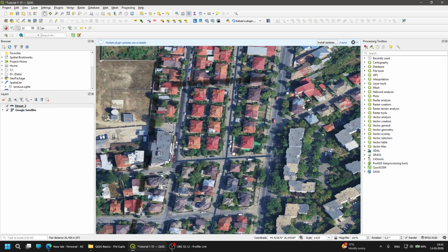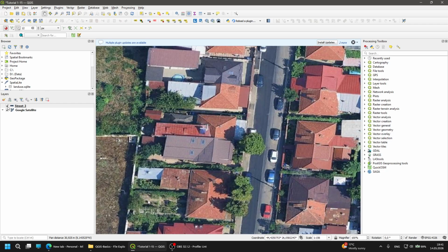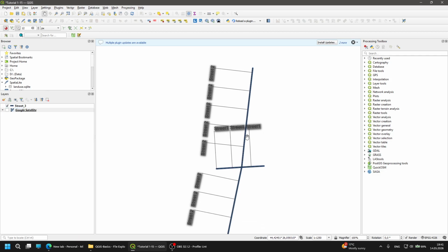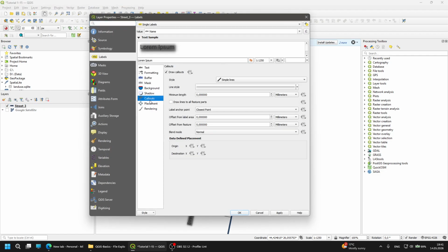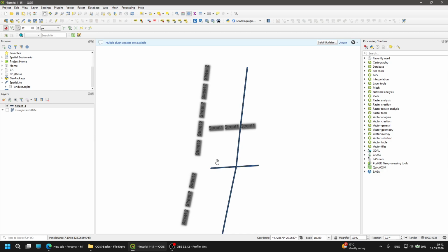And we have callouts. You can see the lines. Let's just click on this one. This is with a callout, meaning that you will have an arrow that is sent to your element. If we go back to properties, go to callouts, and just disable that one and click OK, now we can see that the labels at a distance from our elements are shown.